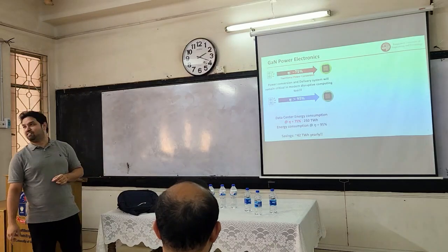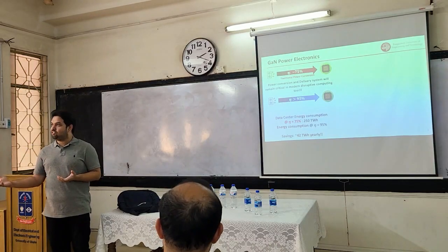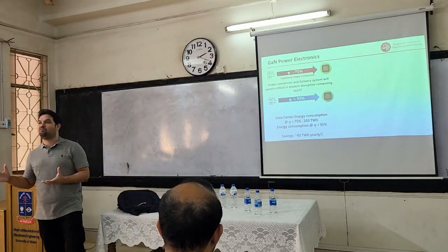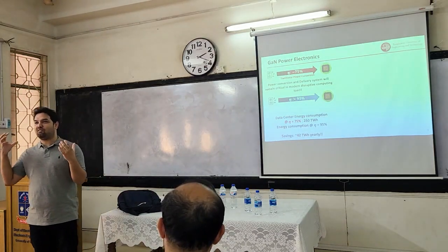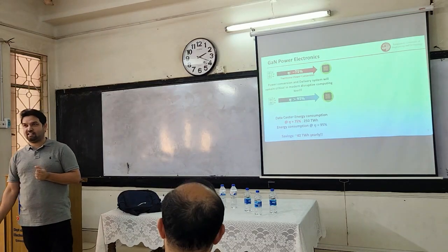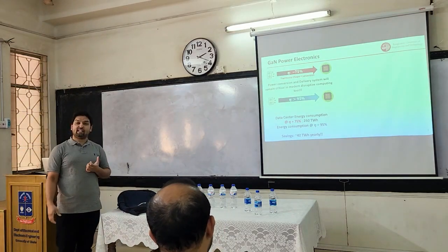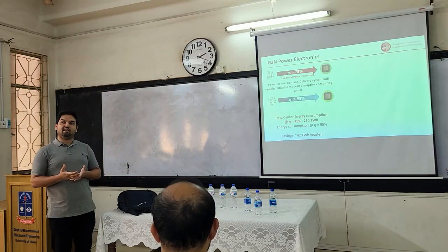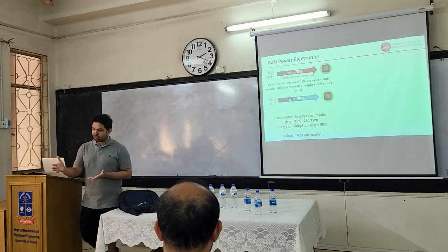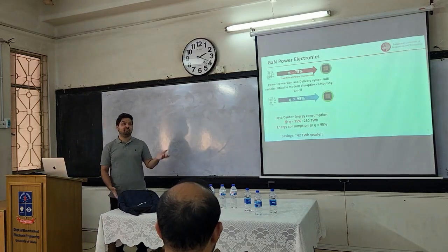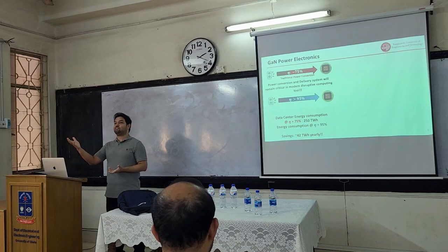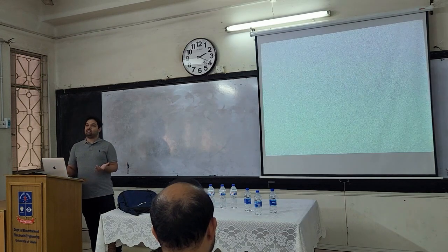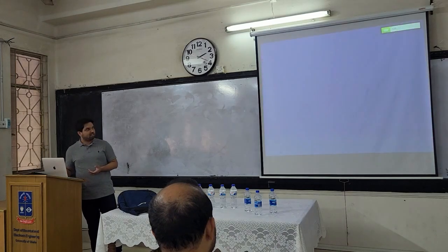So all of this conversion actually is not that energy efficient. Right now it's around 75% efficient. That means you are losing 25% of the power there. So 25% of the power never reaches the processor. But we can change that. We can make it more energy efficient, and right now we have some work with Chancellor to show that it is possible to make these converters up to 98% efficient. So there is a huge room for opportunity there. And we're talking about in the range of trillion watts of power.